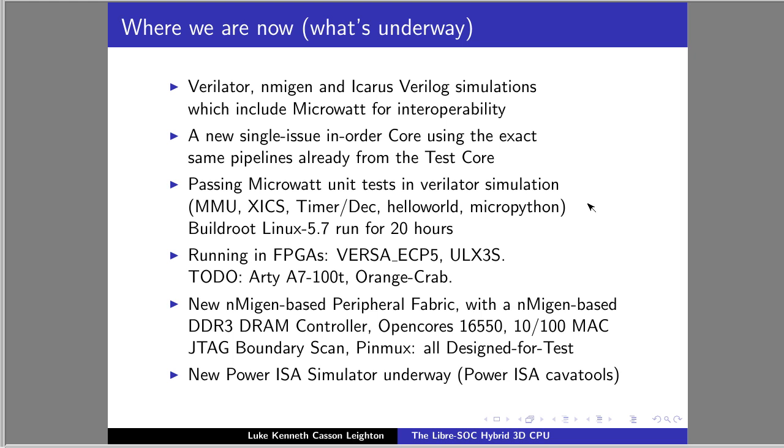They've assumed a certain level of functionality has been achieved, and so they are basic bare metal programs. The Hello World, I think, is something like 1,800 bytes. It includes initialization of a UART 1650 and prints, hello microwatt, it works. But you have to upload that into a simulated SRAM, and that's where the microwatt mini SOC fabric comes into play. It's called soc.vhdl. If you look at the source code of it, you'll find it puts everything together.